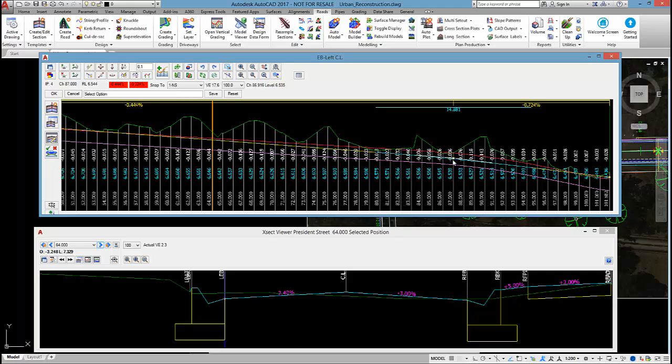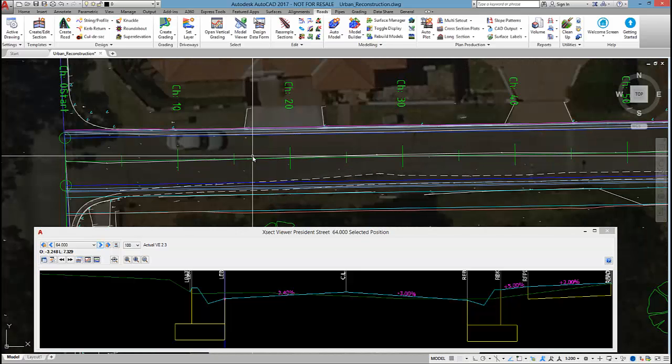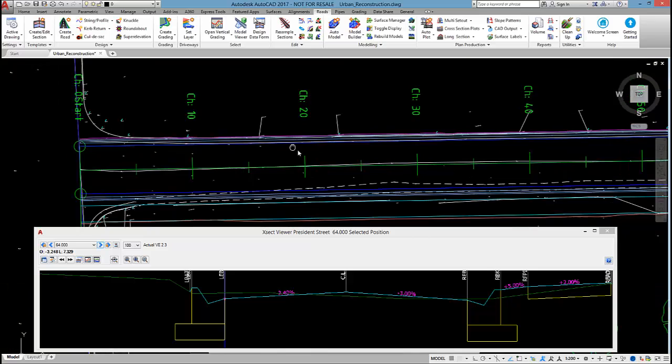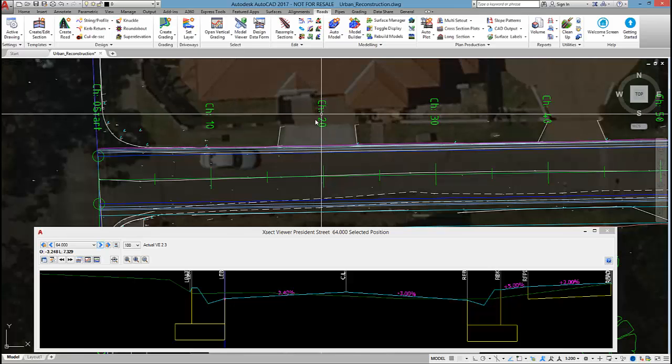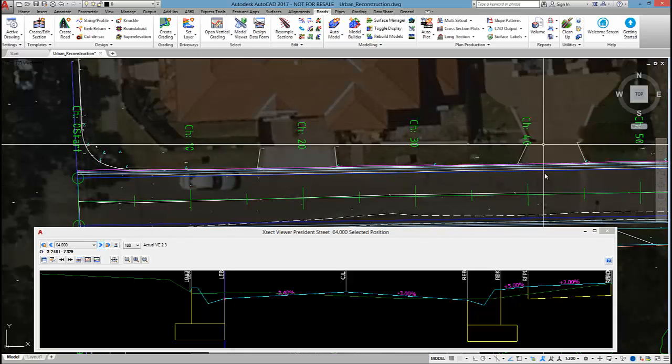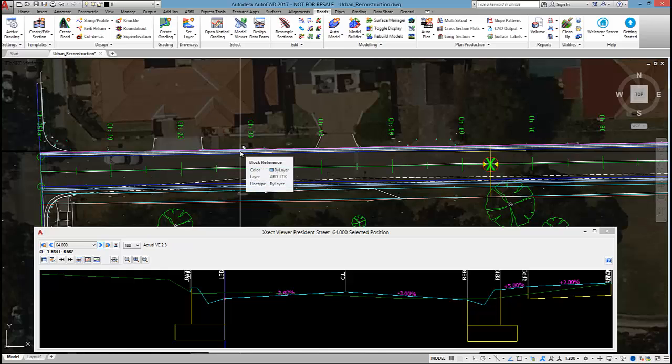Now, the other useful command that we could use to ensure a suitable design is run the driveway checker. I won't do it in this video, but we do have this command well documented on our YouTube page, but I could set up the locations of the driveways, and then as I'm redesigning the curb, the software's running the standard B85 or B99 vehicle, and doing that check for me. So that's another thing that I could do on this project, but I won't.